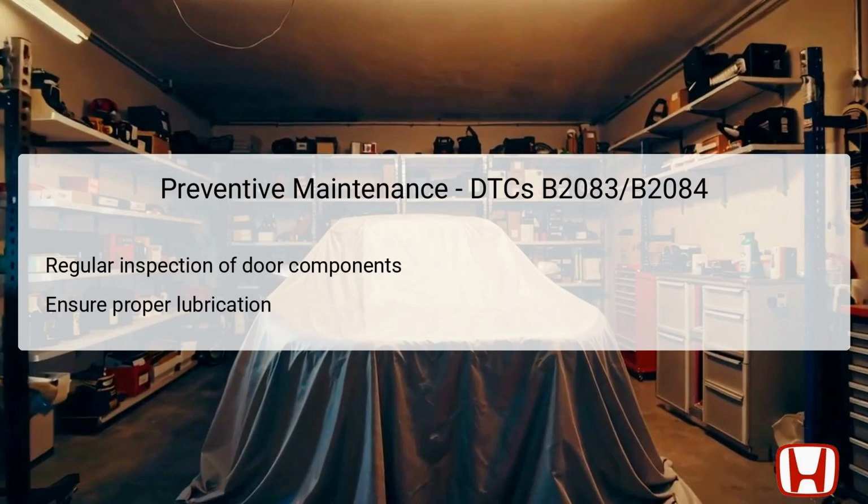Additionally, ensuring proper lubrication at the joints and moving parts of the door assembly ensures smooth operation, reducing the risk of stalling or unresponsive behavior. Scheduling these maintenance checks on a regular basis, perhaps alongside standard vehicle service intervals, helps ensure that the sliding door continues to function optimally. Preventive care ultimately saves time and costs associated with repairs.